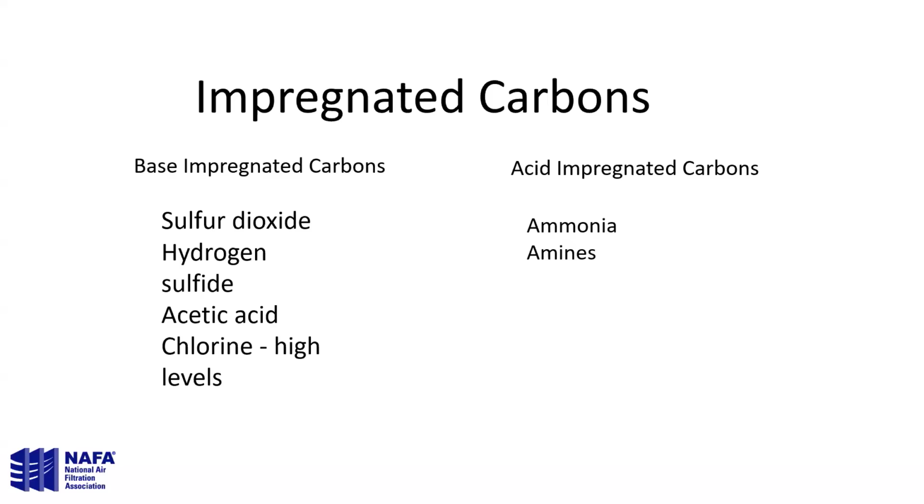And then we have our acid impregnated carbon, and this is pretty much the only product that'll work very well on ammonia and amines. And I'm sure there are a few of you out there who've always seen the term and heard the word zeolite, and it was made famous many, many years ago by Honeywell. Zeolite works great in water. It does not work on ammonia in air. It has about a 2% capacity. But it was a great selling tool, and they did a great job. But unfortunately, that myth has continued on. If you have high levels of ammonia and amines, you cannot use a zeolite to remove it.